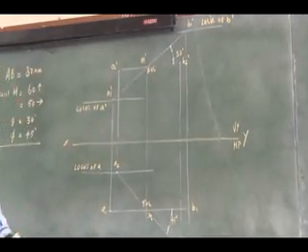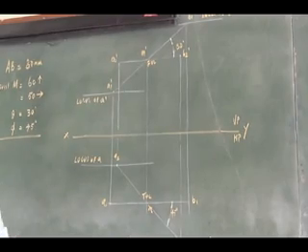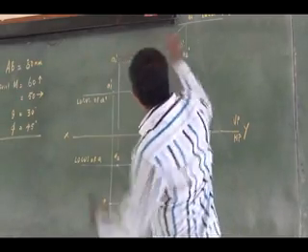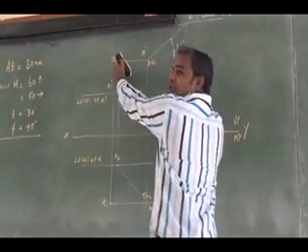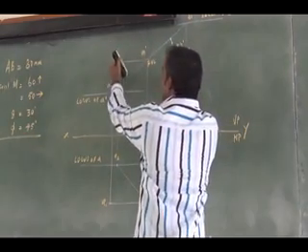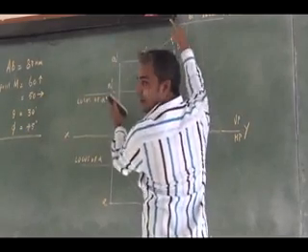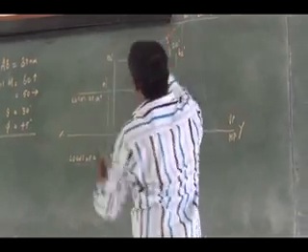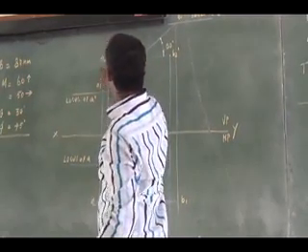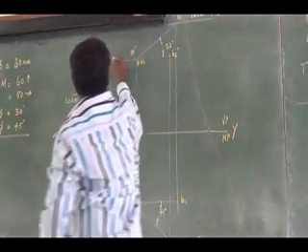right? So just as a simple one, you can rotate any one. See here, the whole thing A, front view length, I have to rotate the whole thing about M like this. So instead of rotating the whole thing, what I can do is just use M dash as center and A2 dash as radius, and rotate this in a clockwise manner.